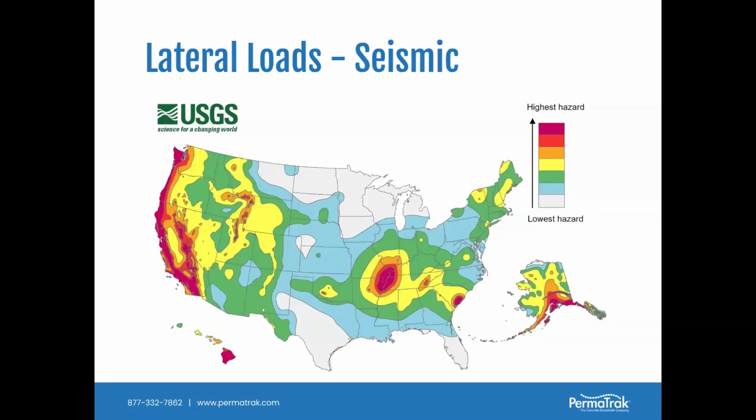Another lateral load is seismic loading. We get asked this question quite often. And yes, seismic load sometimes does govern, as you can expect, probably only in those red areas where there's high seismicity on the West Coast, down in the Charleston area in the Southeast, certainly in Hawaii and around Memphis. That is going to be left up to the structural engineer to decide, how does the seismic load compare to the lateral load? And the one is going to govern over the other.